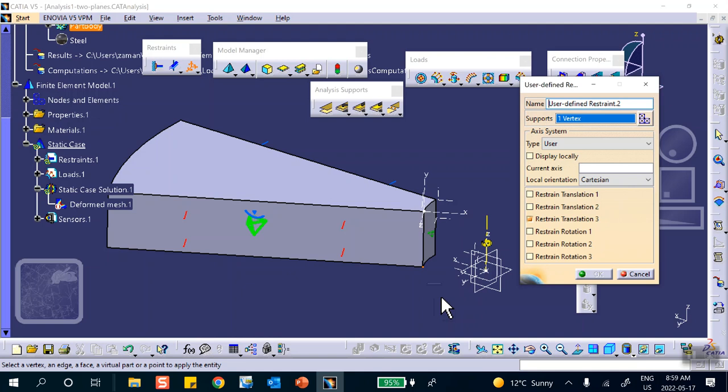Here, definitely different. The local one has Y. The global one is Z. So if you want, you can use Y of the user, because notice it's there. Or you can say global direction Z. Don't go up and down in the Z direction of the global coordinate system. And if you make a mistake, it will show on these plots, like this. See that red arrow in the corner? If you had selected the bad coordinate system, bad direction, you show in the direction that you immediately realize there's a problem there.